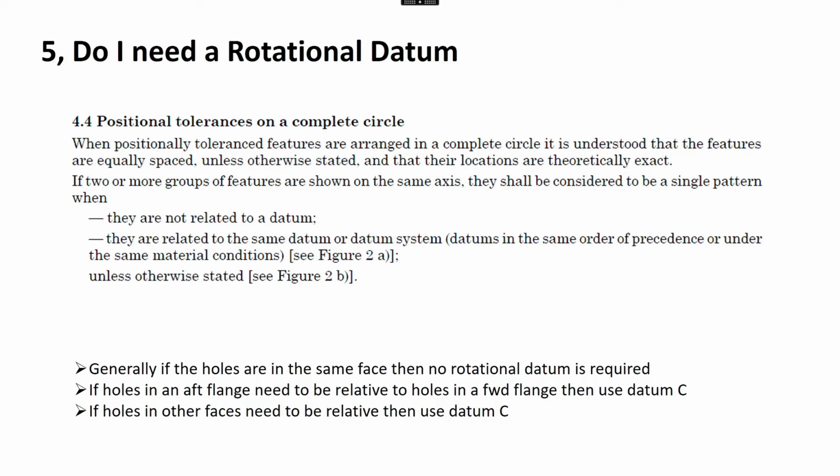I think generally speaking, I wouldn't use a rotational datum if the holes are in the same face and you want the holes relative to each other. You don't need a rotational datum. It should be treated as one pattern, and that's basically what the standards are saying.